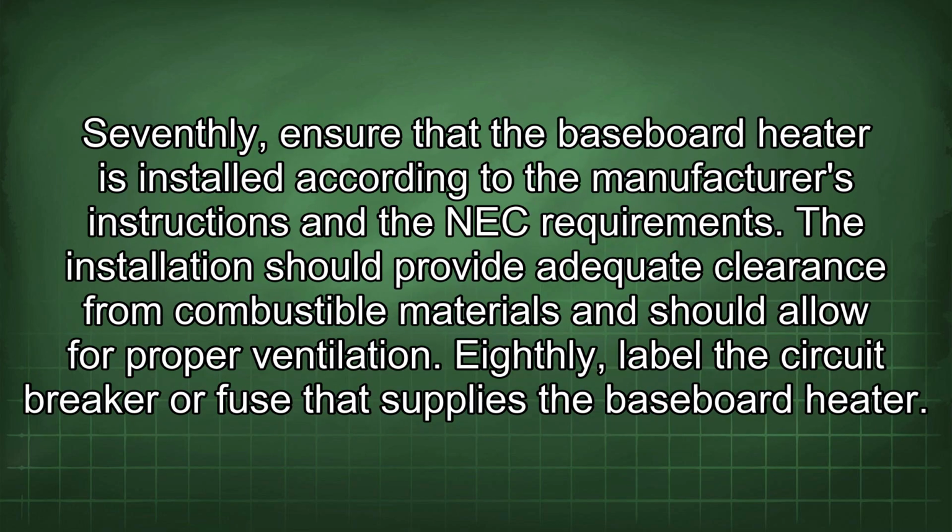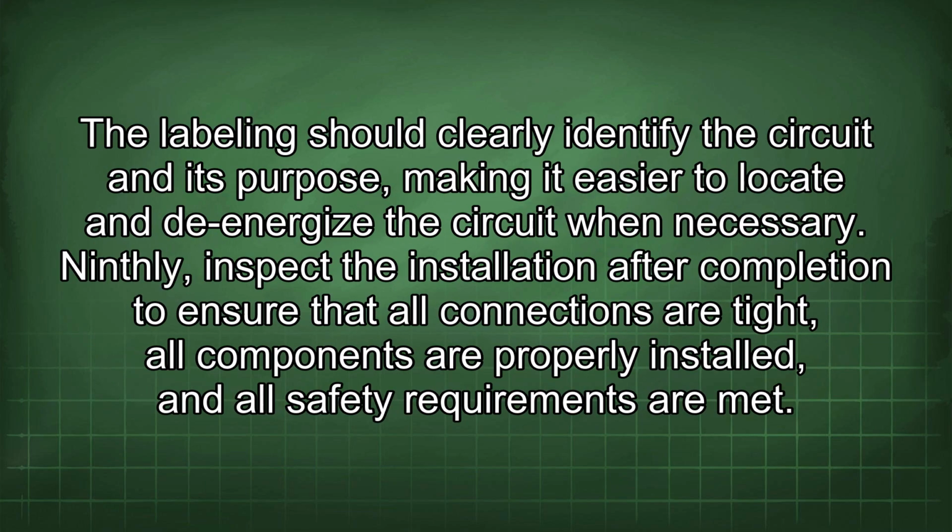Seventhly, ensure that the baseboard heater is installed according to the manufacturer's instructions and the NEC requirements. The installation should provide adequate clearance from combustible materials and should allow for proper ventilation. Eighthly, label the circuit breaker or fuse that supplies the baseboard heater. The labeling should clearly identify the circuit and its purpose, making it easier to locate and de-energize the circuit when necessary.